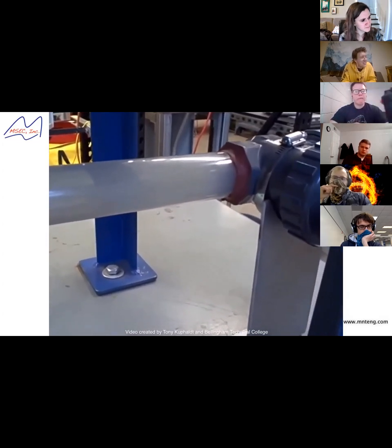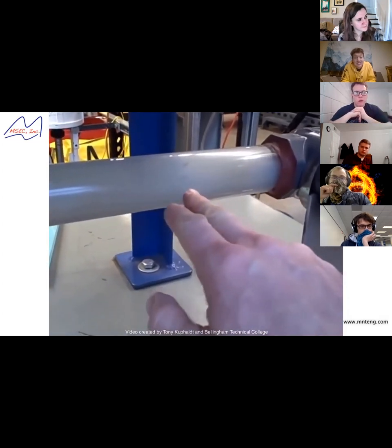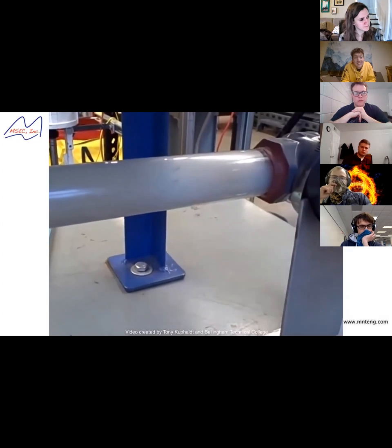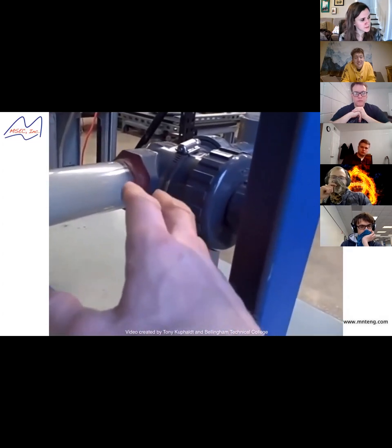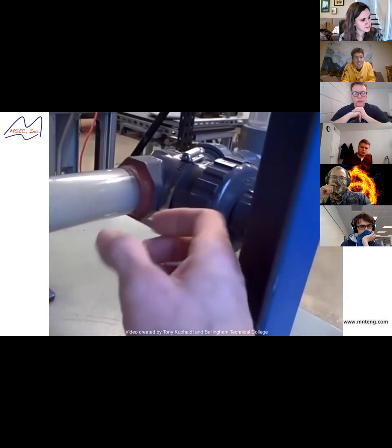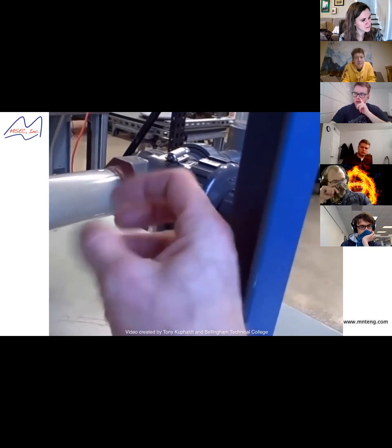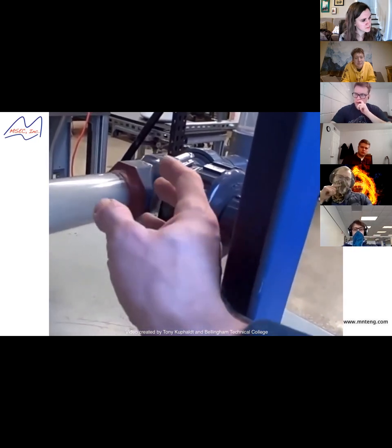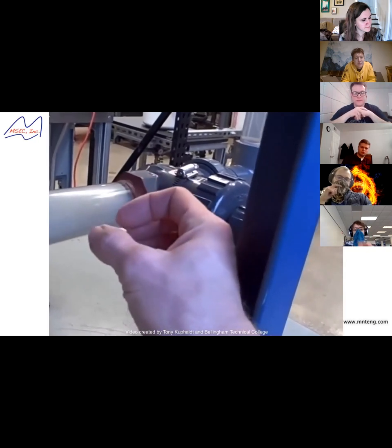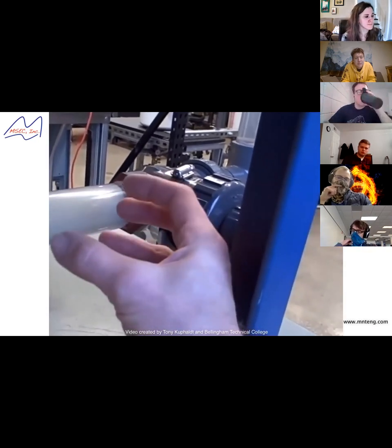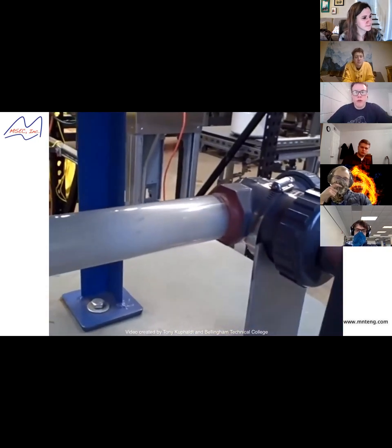You can really hear it now. You can see it occur inside of here. It's a very pronounced action and noise. As the water goes through the valve, it reduces pressure going to the restricted valve. Its pressure drops below the vapor point of the water at this temperature. It flashes into steam, and then after it comes out of the valve and expands again, the pressure goes up, and what happens is those vapor bubbles collapse back into liquid, and that's when we get the cavitation effect.